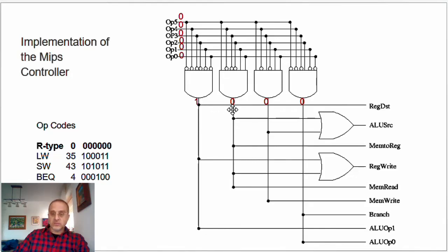Here we see that we have a 0 because some are inverted, but some are not. So that's already going to tell us it's going to be a 0. This is an AND. And also here some are inverted and some are not, so it'll be 0. And here all of them are inverted except for 1, so that's also not going to work; the AND is going to produce a result of 0. Because in other words, the only time I'll get a result of 1 is when they're all 1s, because it's an AND. So then I have on these lines 1, 0, 0, and 0.